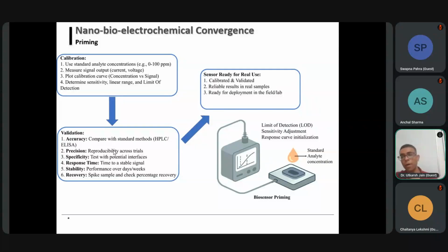For instance, if you are working on a glucose sensing device, since glucose is abundant in our blood, and the enzyme-based sensor uses glucose oxidase coated on the screen-printed electrode, then the enzyme concentration should be properly measured, and for a particular area on the working electrode, how many glucose molecules it is binding, and what is the limit of detection, whether it is a sensitive approach or not.